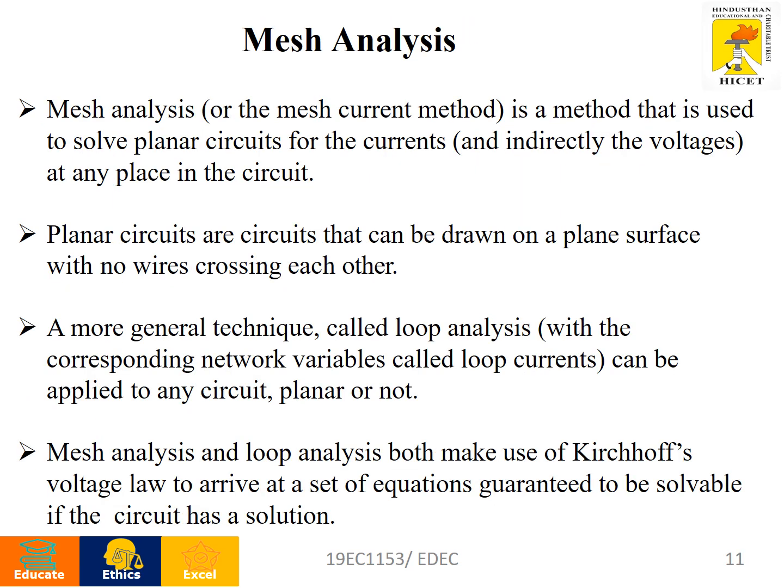The next one is mesh analysis. Mesh analysis, or the mesh current method, is a method used to solve a planar circuit. So what is a planar circuit? Planar circuits are circuits that can be drawn on a plane surface with no wires crossing each other. There is a more general technique called loop analysis, which can be applied to any circuit, planar or not. Mesh analysis and loop analysis both make use of Kirchhoff's voltage law to arrive at a set of equations guaranteed to be solvable if the circuit has a solution.